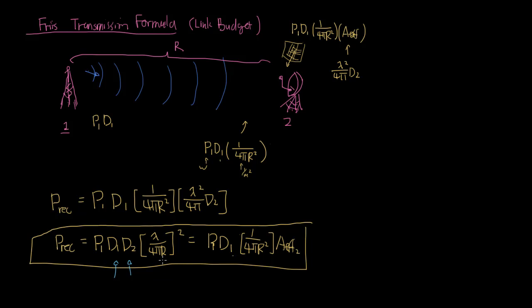and receive antennas. And so what that means is that instead of a light bulb where you can transfer waves in every direction and get away with it, now you have something that's more like a laser beam. A pencil beam that you need to point in order to have the gain needed to make up. And separately, on the receive side, here's this person with their fancy 5G phone. Their 5G phone is also going to have a high directivity antenna for this link budget to work.